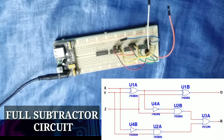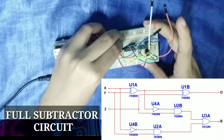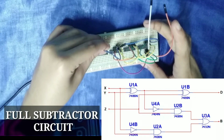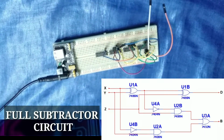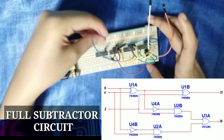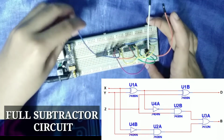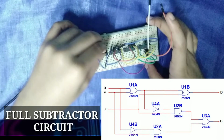Now, for the 7432 connection, we need to connect pin number 3 of the 7408 to pin number 1 of the 7432. And lastly, we need to connect pin number 6 of the 7408 to pin number 2 of our 7432.